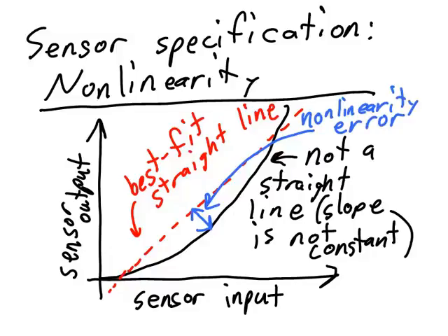It's best to have a sensor with the most linearity that we can find. In other words, we don't want to use a sensor with a lot of nonlinearity error. When we purchase a sensor, it typically shows the nonlinearity error in its data sheet. However, the nonlinearity error that is quoted in its data sheet is only accurate as long as that sensor is being used to measure what it's intended to measure. If we use a sensor to measure some other property, then we might have to find out the nonlinearity error ourselves by testing the sensor.